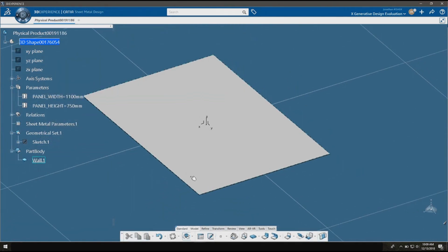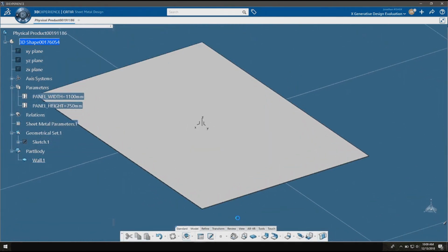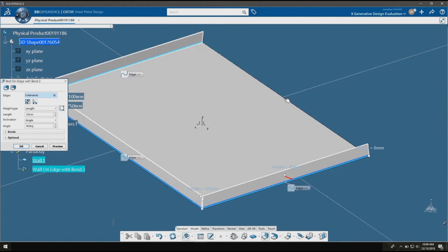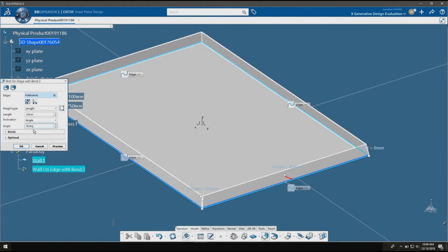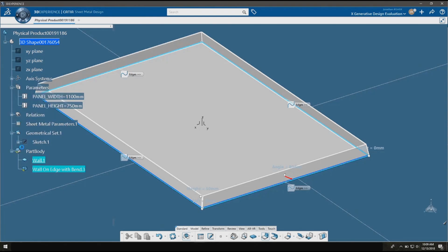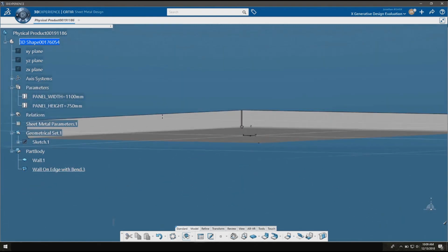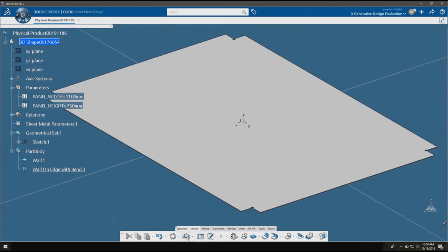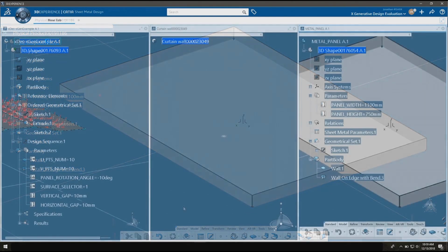And now I'm going to create a new part using the sheet metal design application. The sheet metal design application will allow me to make this panel, and it does the calculations for K factor for folding and everything like that. It does the notching based on the machining requirements. It includes an unfold view that I can project into a drawing for manufacturing.